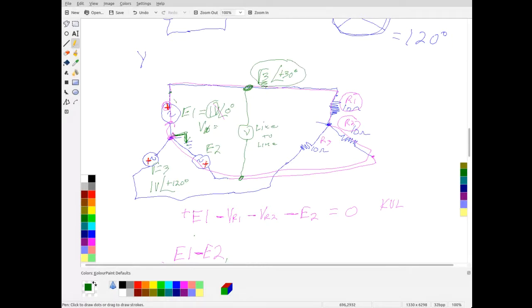Okay, so this is the change when I look at just this 1 voltage here. It was 1 volt angle 0 degrees. When I measure the voltage from this line to this line, it's the square root of 3. So it's bigger by the square root of 3.